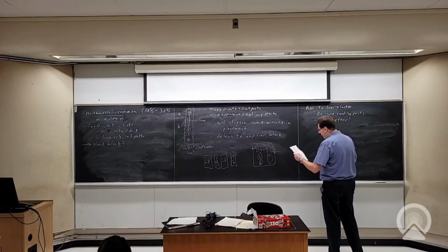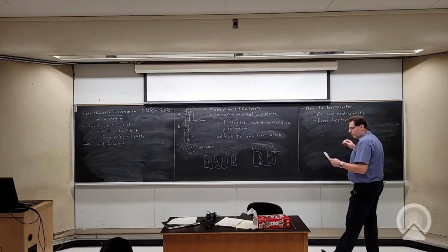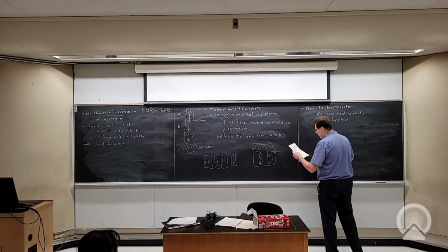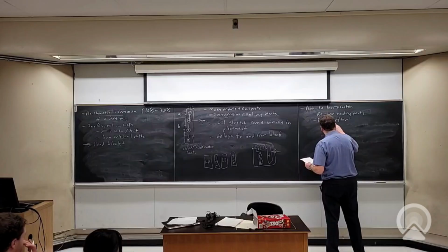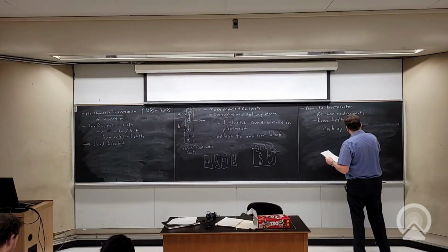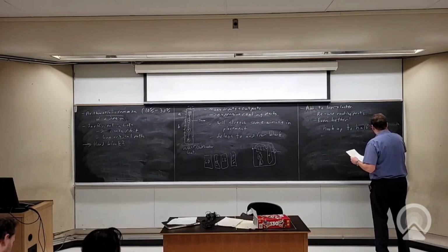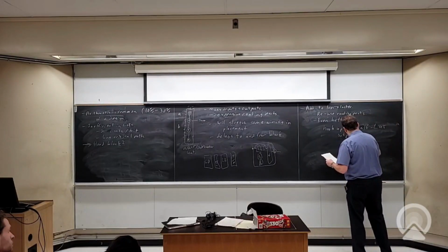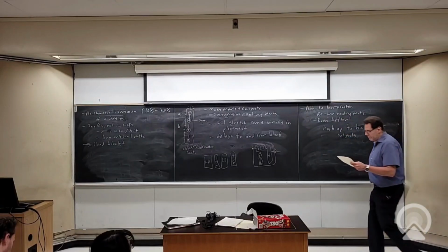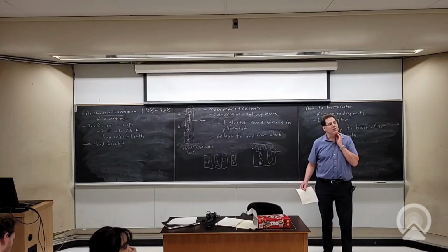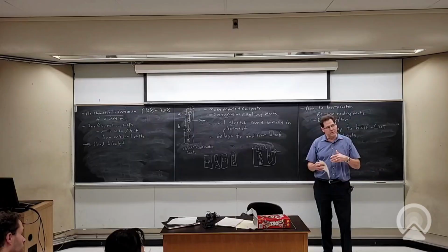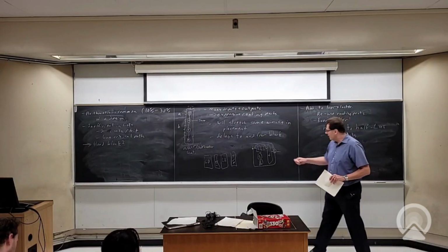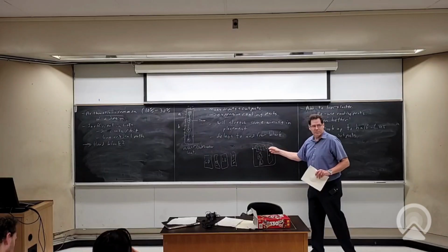Okay, so even better, I'll show you what most Altera chips do, and many other chips do, but there are a lot of variations on this theme. But they're all reasonably similar. So what I want to do is hook up to, I'm going to call them half LUT outputs. Okay, so this half LUT output, what do I mean by that? Essentially, it's what Adam suggested earlier. What if we decompose more? We take our LUTs and we treat them as 2 smaller LUTs. We're going to use that trick again. And we're going to use it to get little bits of logic in front of this adder.